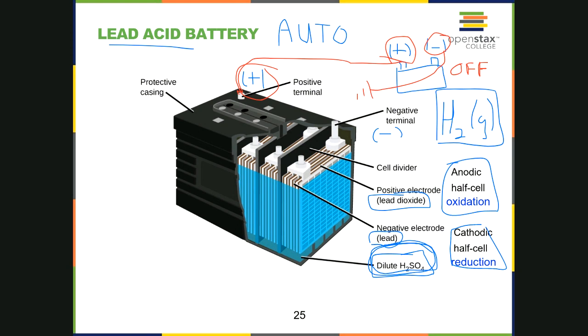In other words, you're looking for a bolt or a bare piece of metal on your car that you can clamp the cable to, and you want this to be away from, you want some separation between where you're making the connection and your battery, so that if it causes a spark, you don't ignite the hydrogen gas and you don't get injured.